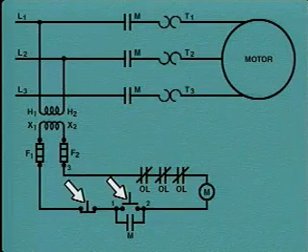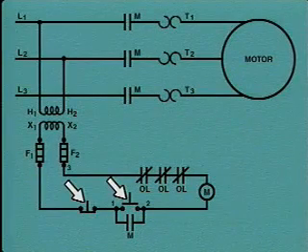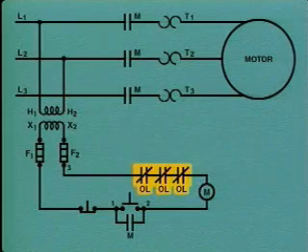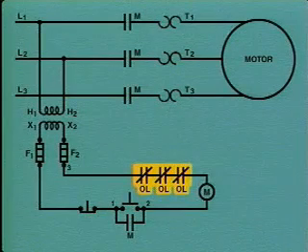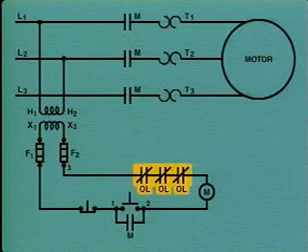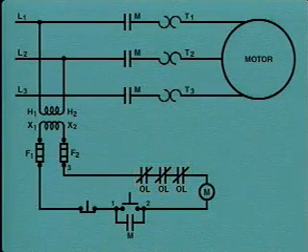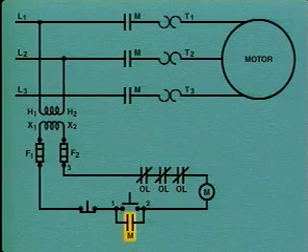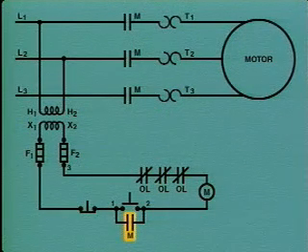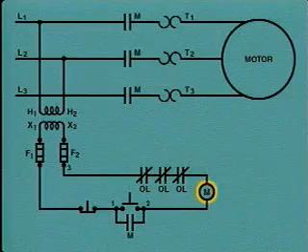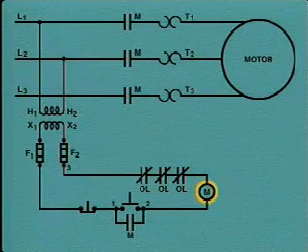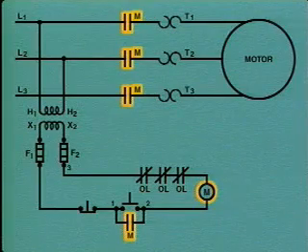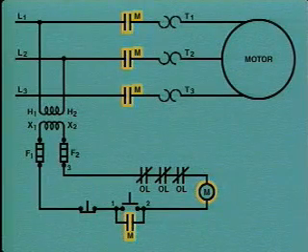The fuses are connected to stop and start buttons and to overload contacts. The overload contacts, which are labeled OL, are normally closed. The start button has maintaining contacts, labeled M. The maintaining contacts are auxiliary contacts operated by the M coil, which is also in the control circuit. All of the contacts labeled M are operated by the M coil.